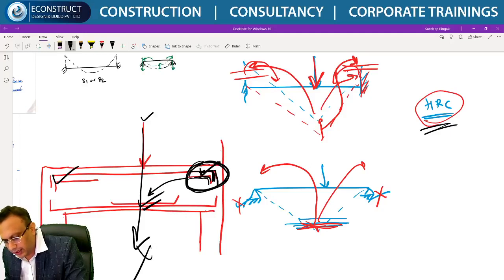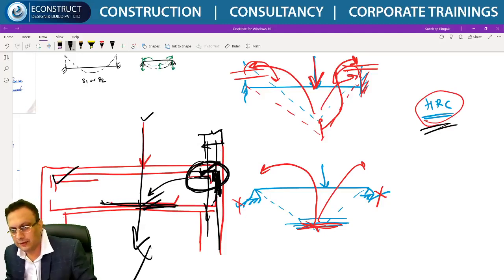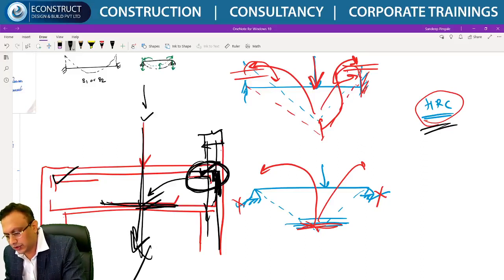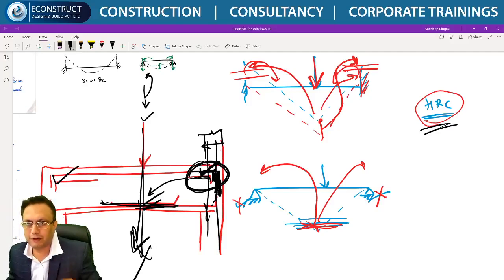If you are not sure that the extra rebars or anchorage will be there, because sometimes the size of the columns is very small, this length is very small, and there are rebars in the columns also, so you are not sure that this much anchorage length will be possible. Okay, no problem, you design extra bottom steel for that, so there is no excessive settlement which will create strain in the building. If the settlement happens, it will transfer that strain to the upper floor, right?